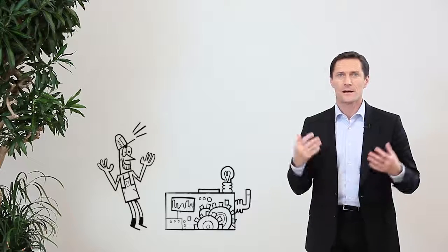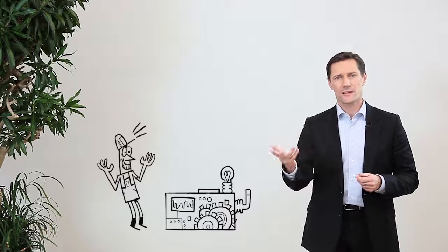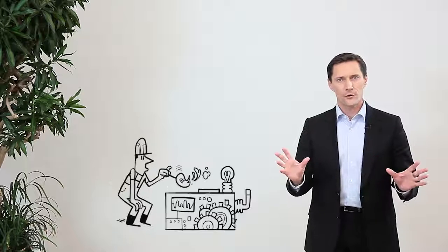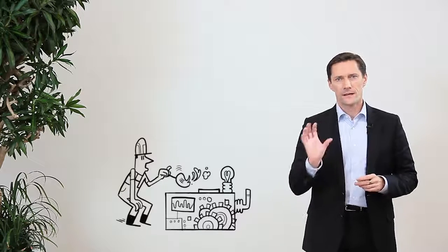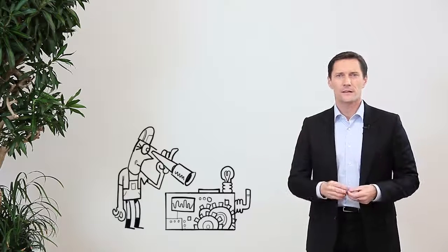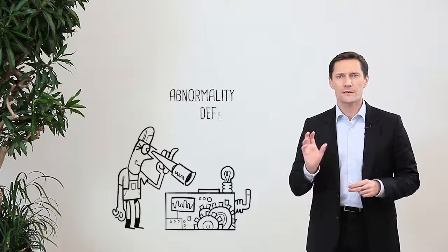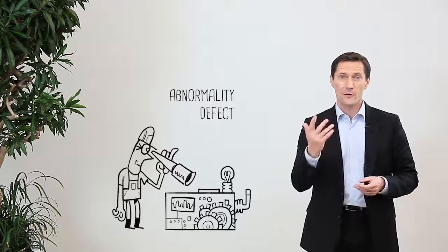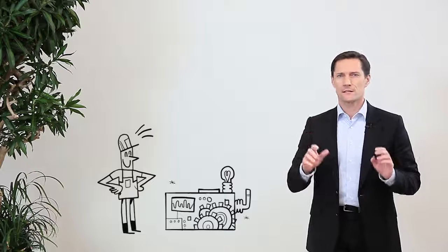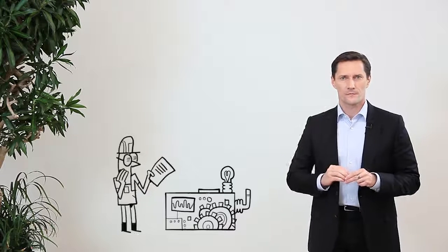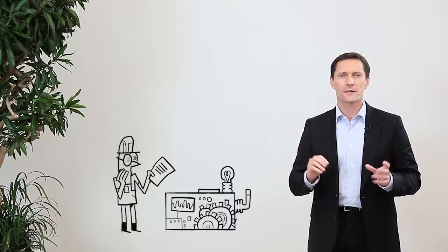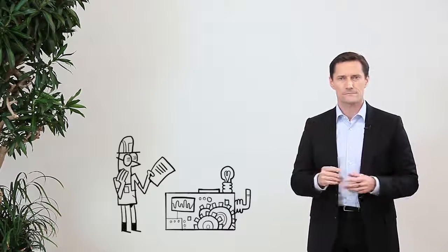So finally, autonomous maintenance, it's not about machines, although it sounds like, but it's about developing the right capabilities. So the employees act as owner of the equipment. They take care of the equipment by proper operation and daily checks. Key concepts is to identify any abnormality or defect on the equipment and, even more important, to fix it. The equipment needs to be kept in a clean, tight and lubricated condition. To do that, operators follow clear autonomous maintenance standards to maintain and improve the performance of the equipment.